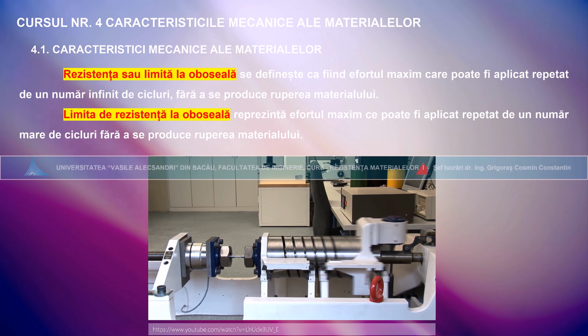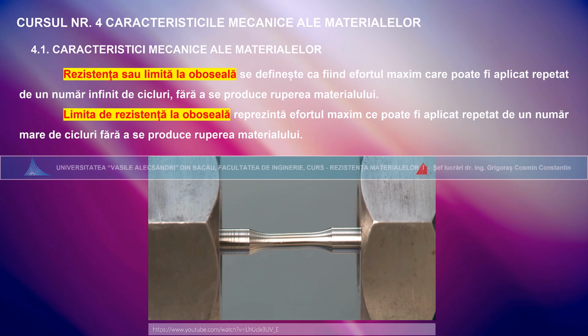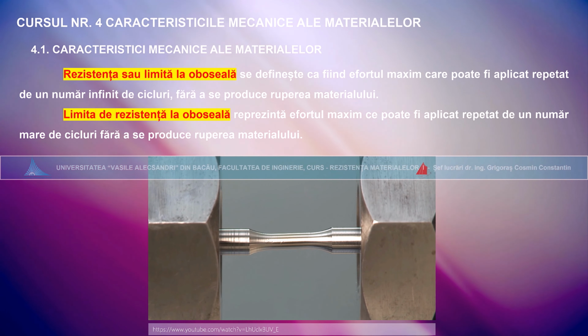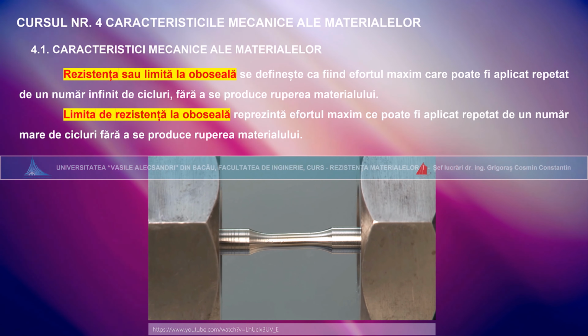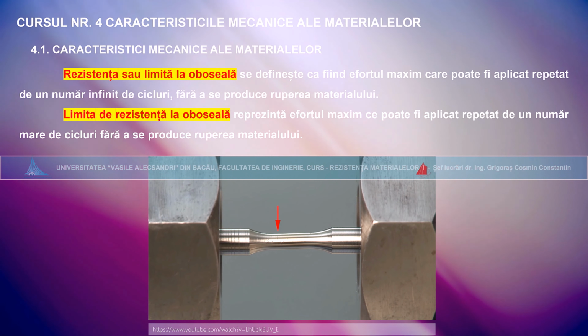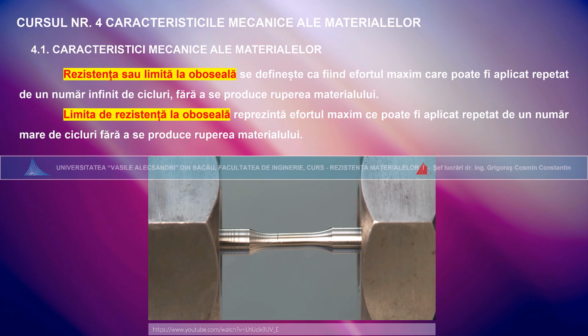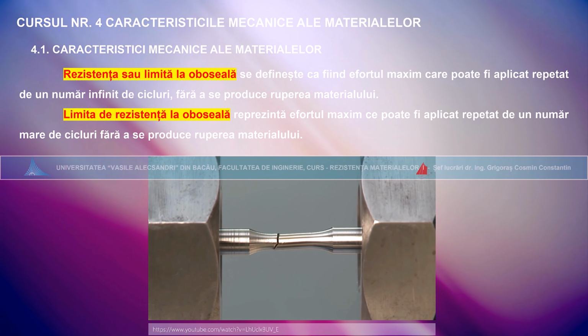Meanwhile, the first specimen has already endured over 300,000 load cycles and still seems to be intact. In reality, however, several cracks have already developed starting from the surface, the so-called fatigue cracks. With each load cycle, they grow a bit further into the specimen. The biggest crack gains the upper hand, grows the fastest, and finally leads to fracture after 381,000 load cycles.